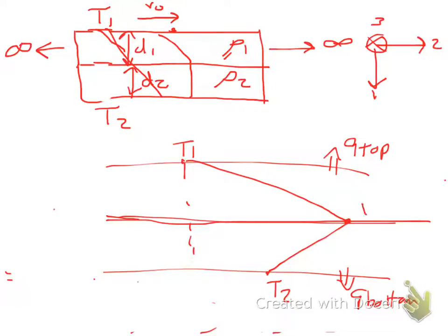At this point, T of our source depends on how big of a friction coefficient we have, how much energy we're generating. We don't know this, but we could find it if we knew the Q of the source, so the heat we're generating at that point along that line.